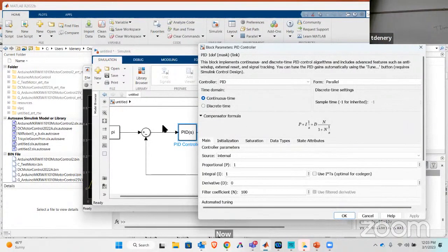Now, there's this whole S. You guys know what the S is there for? Exactly. So Laplace transform. And controls engineers love Laplace generally, all right? It means that they turn hard differential equations into almost algebra. It's a super clever idea. And essentially, that error will be multiplied by a proportional gain defined there. We're going to integrate that error. It's a really cool idea: if I had gravity acting on this thing, it's this integral term that would detect that there's something systematic that's leading to an error. So, and it's the hardest one to explain.